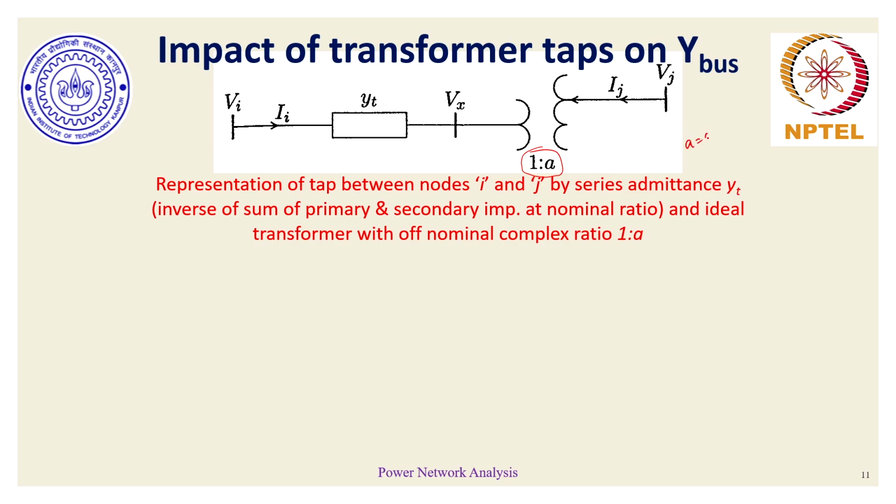It can also be a complex number depending on whether the transformer is regulating only voltages or whether it can also regulate phase shifters. And when A is equal to 1, we call the transformer tap to be at a nominal position. Usually A need not be equal to 1, and that's how it is called off-nominal position. Again, all this discussion is happening on per unit basis.